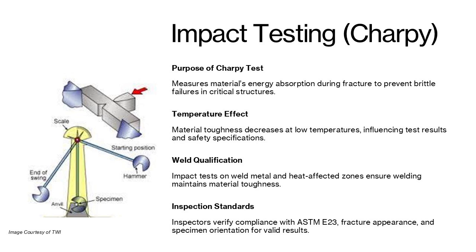The Charpy test evaluates the energy absorbed by a notched specimen when struck by a swinging pendulum. The resulting impact energy reflects the material's ductility and crack arrest capability. Inspectors should understand how test temperature affects results, as many materials exhibit reduced toughness at lower temperatures.